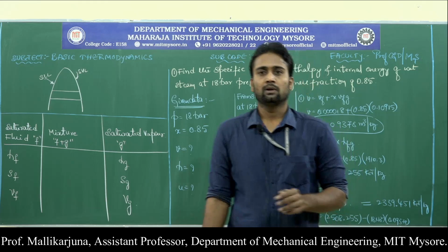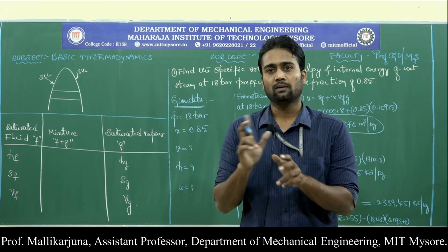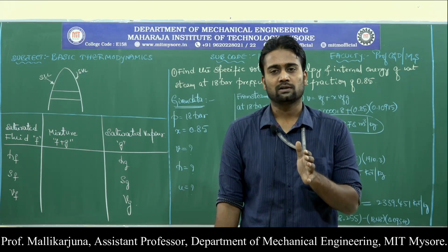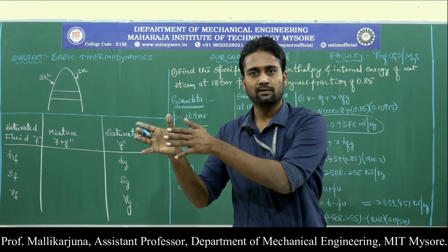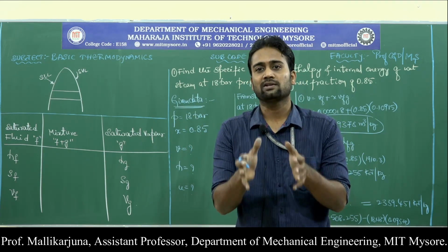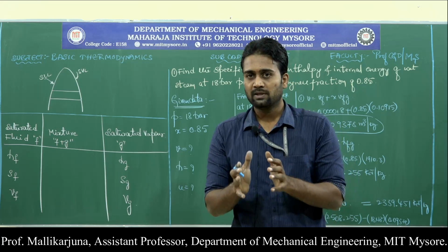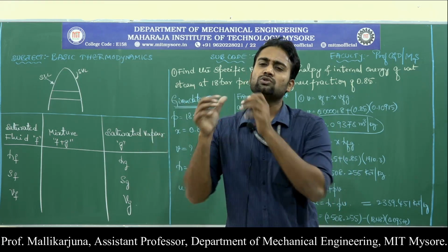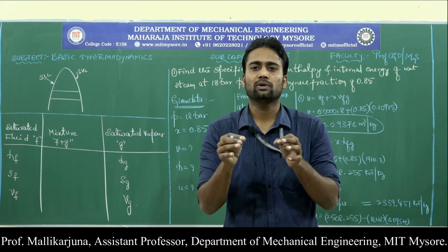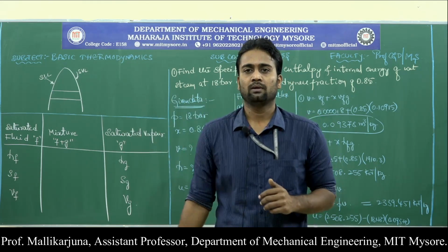We know that in pure substances we will be dealing with two phases, or a mixture of two phases, of the substance. Those are nothing but liquid and vapor. These are the two phases, and liquid plus vapor is the mixture region, the wet steam. In most situations, we are not going to deal with pure liquid. In almost all situations, we will be looking at either the liquid plus vapor region, or the vapor region.